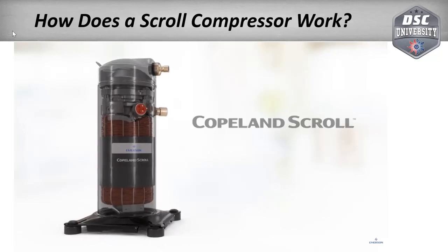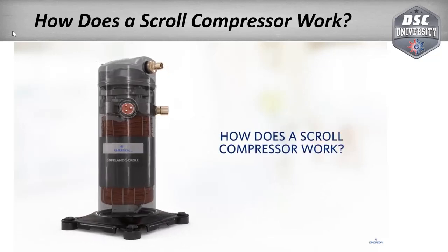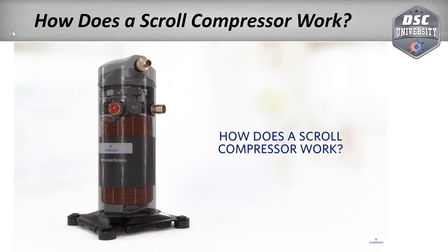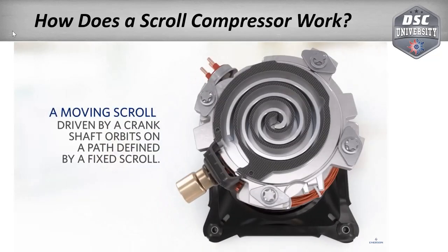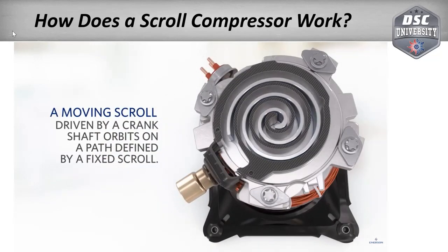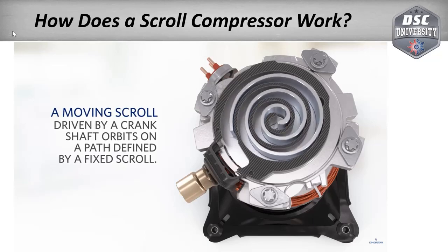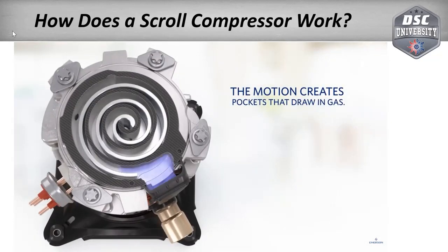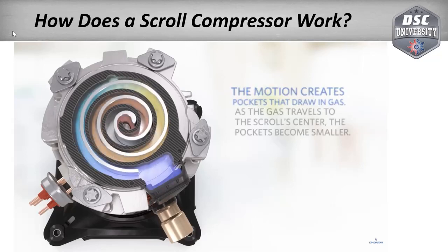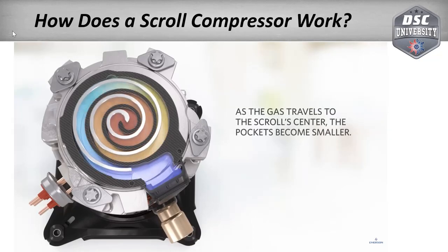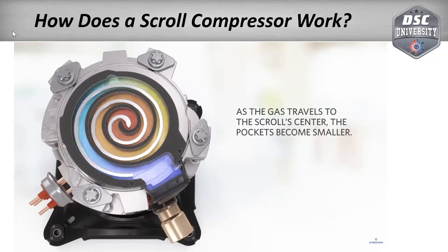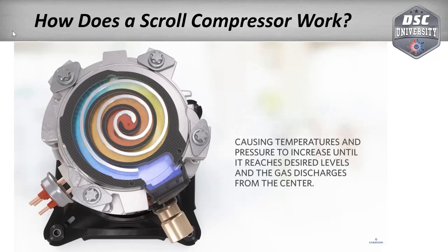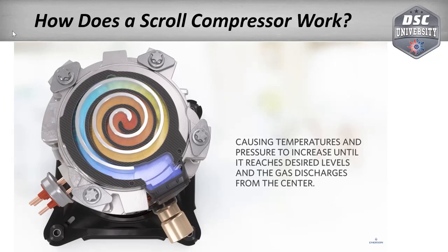This gives you a little bit more of a complete exploded view of what's going on inside the compressor. So pull gas in through the bottom left, spiral it around till it gets to the center, and then it actually goes out through a hole in the top of the plate there. So that is the actual scroll? Mm-hmm.